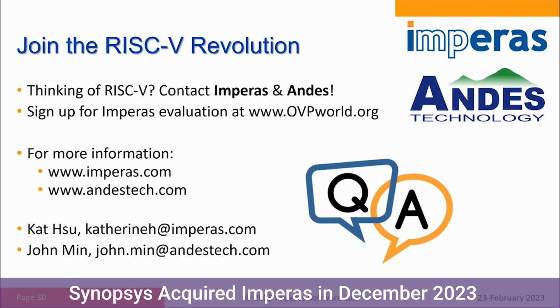Can you please share what kind of custom extensions Andes have on top of the latest RISC-V core? So basically, we have standard extensions, right? On top of RISC-V, we have CoDense for reduced code size. We have StackSafe to protect against stack overflow and underflow bugs. We have PowerBrake for power management and software-controlled frequency scaling of the pipeline. Those are called standard extensions.